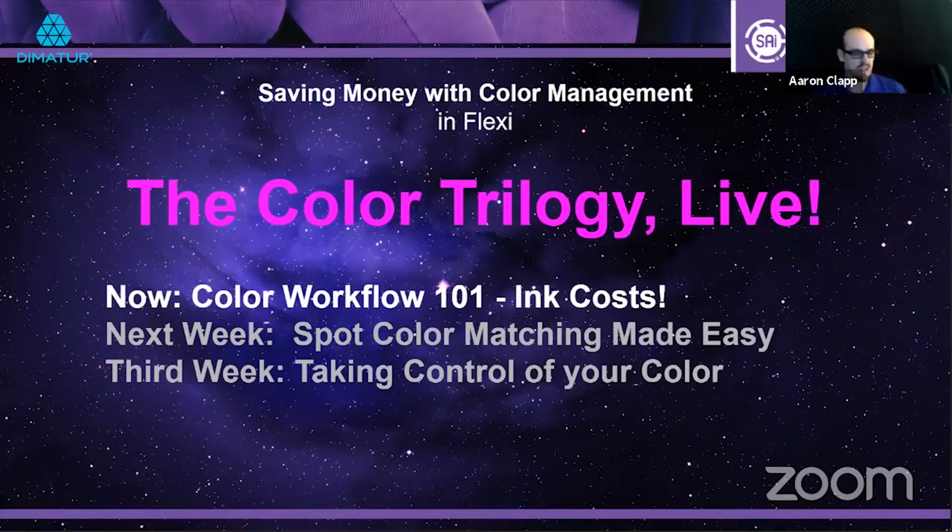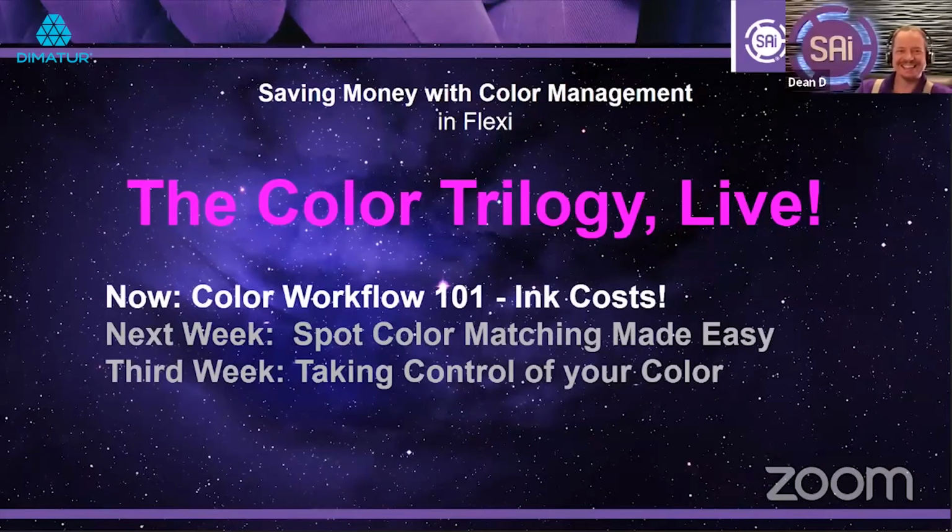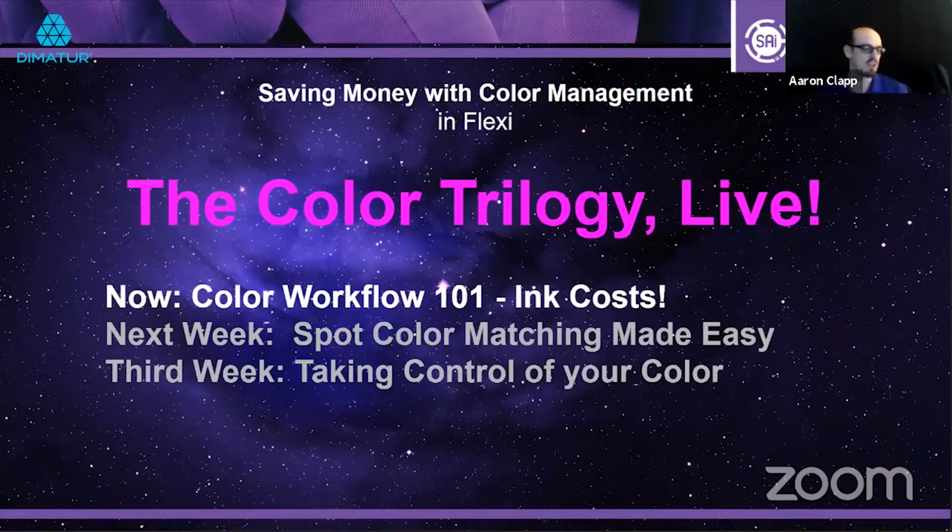Another question came in from, funny enough, a different Doug. He had a question about an image that he was importing. He had a version of Flexi that only does cutting, and he had imported a bitmap and was wondering why it wouldn't cut. We got him up and running, but the problem was that he had a bitmap, and obviously you can't cut a bitmap. It has to be vector artwork in order for you to cut it.